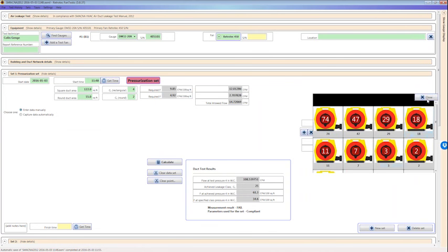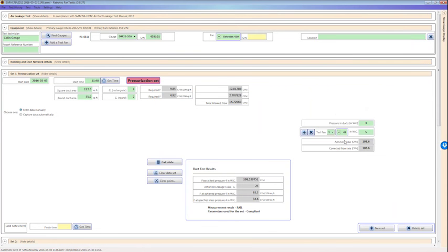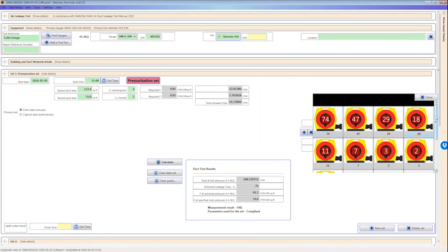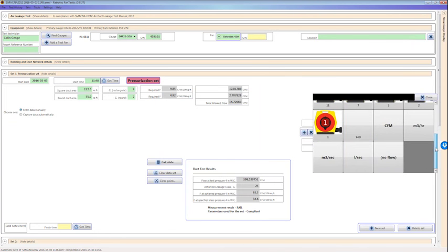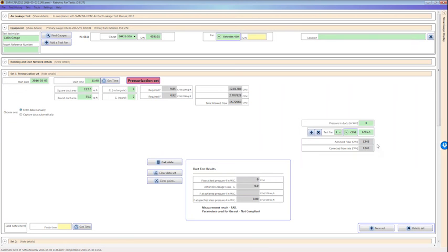So there are some very specialized commercial duct testing applications where you could use those, because nothing comes close to 5,000 CFM in commercial duct testing. I think the biggest one out there is around 1,200 CFM, and it runs on like 250 volts, 3-phase or something. So that's a huge amount of flow, but in general, the answer to that question is no.